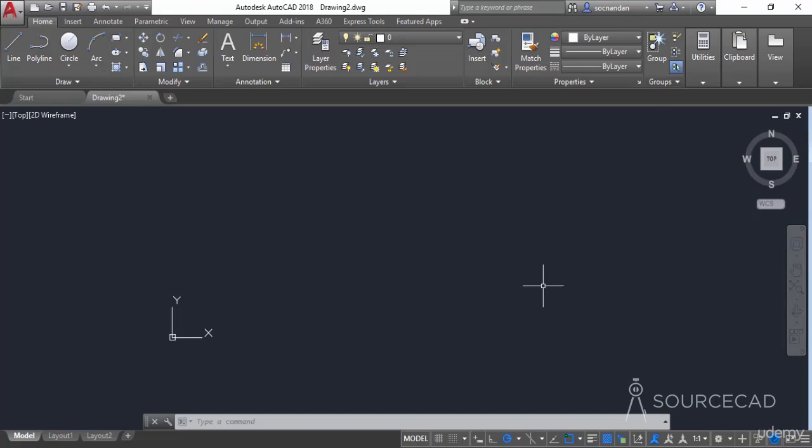Now you can also add grid if it is not present in your drawing area directly by clicking this first icon, which is grid mode. You can also turn it on by pressing the F7 key on your keyboard. So here we have a grid which is mostly like a graph paper. So you can zoom in and zoom out to see its individual blocks. And now here we have these individual blocks. Now currently there are 5 blocks in horizontal and 5 blocks in vertical direction, and after every 5 blocks there is a major line in both the directions.